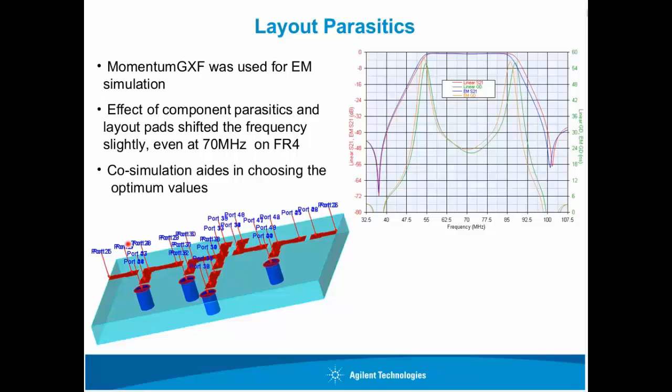You just define the footprints in the schematic, and they're automatically placed, and the ports are associated with them, as we show in the 3D view here. You can see it identifies all the ports that are associated with the footprints. These were not manually placed. Genesys did this automatically. So then you can run the simulation. You don't have to use a lookalike or anything to combine the two simulations.